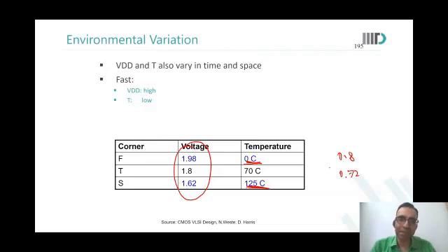Current increasing and VT reducing, one could say that because current has increased, therefore VT has reduced, because the definition of VT is 1 microampere of current for a 1 micron width device. Right?